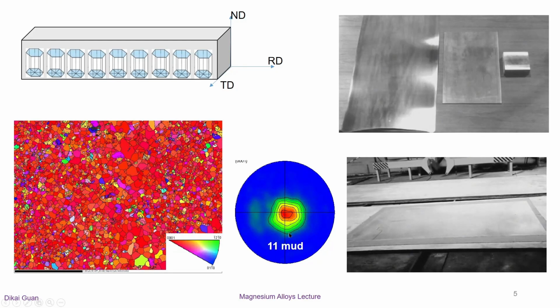The mechanical properties of magnesium sheet metal are mainly determined by the final grain size. Beneficial thermomechanical reactions can be achieved by adjusting work hardening, recovery, and recrystallization effects, which are sensitive to alloy composition, process temperature, deformation parameters, reheating cycles, the final cooling to room temperature, and an additional heat treatment.